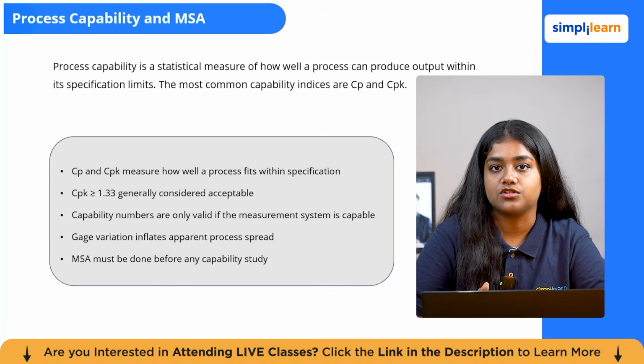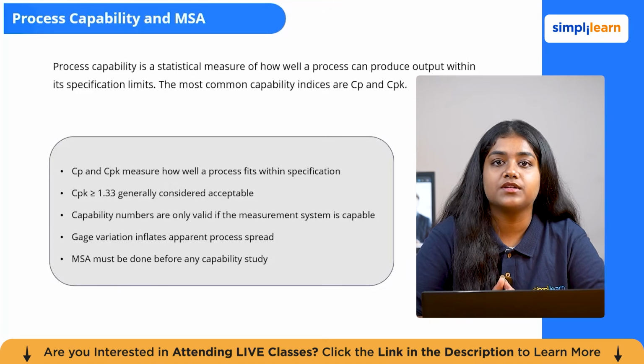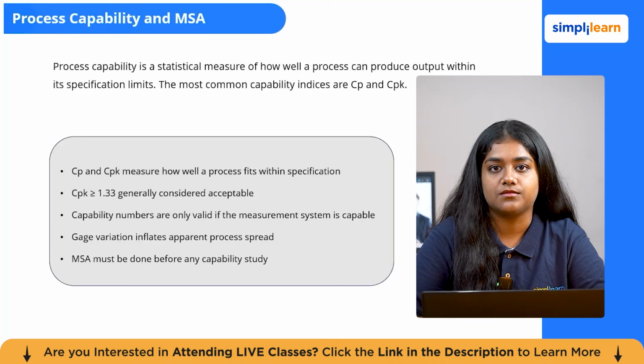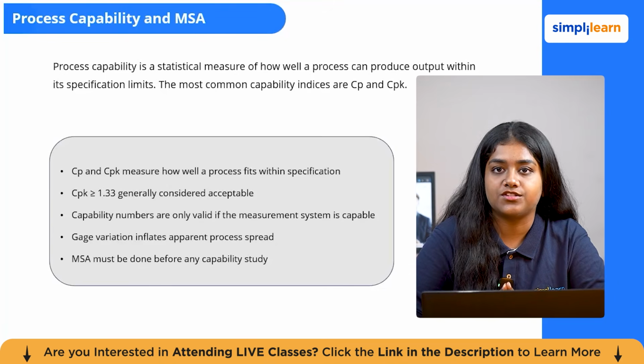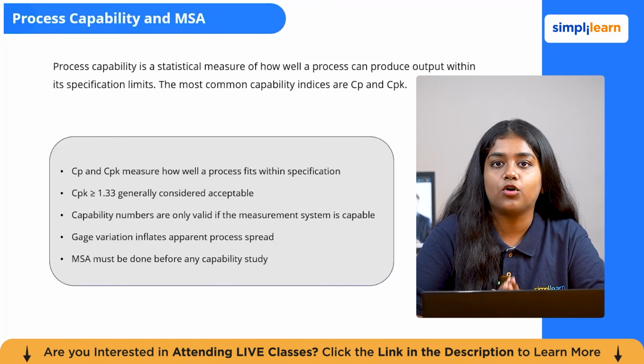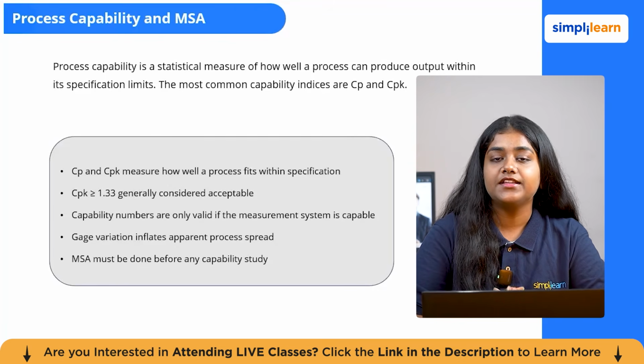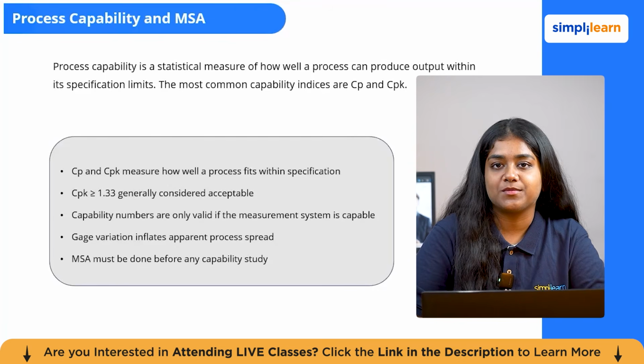So when we talk about distributions in the context of MSA, we are usually thinking about the normal distribution, the familiar bell curve. In a stable, well-behaved process, measurements tend to follow a normal distribution. Understanding the shape and spread of your data distribution helps you see whether your measurement system is introducing distortion. A measurement system with poor precision broadens the distribution. Bias shifts it left or right. Non-linearity might cause it to look skewed. Interpreting these distributions is a key skill in measurement system analysis.